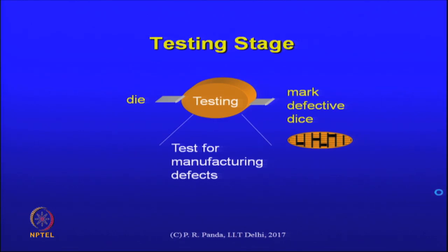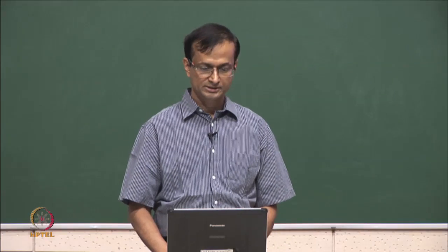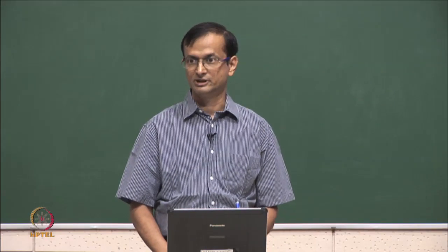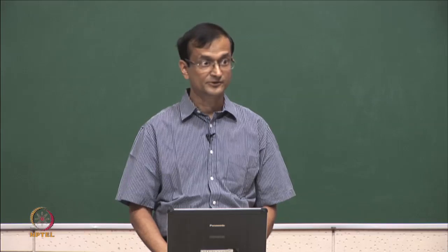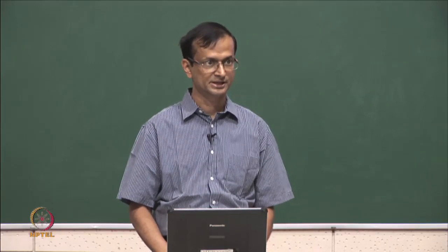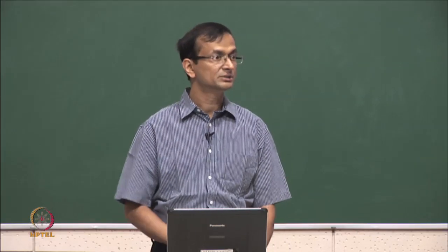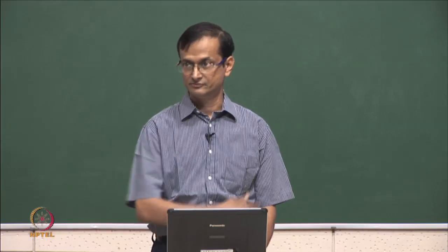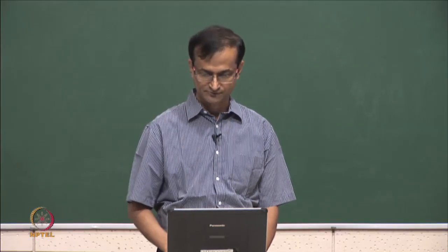This testing ought to be seen differently from the verification and simulation steps that we had seen earlier. Those are on a representation of the chip, whereas this testing is on the manufactured die. Even if everything is fine with respect to the design, there may still be defects in the dies, and we need to catch those in this testing phase.